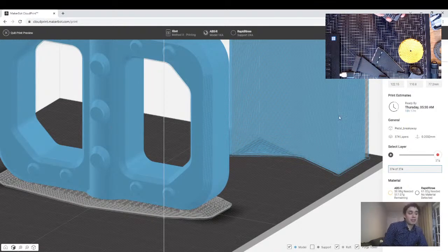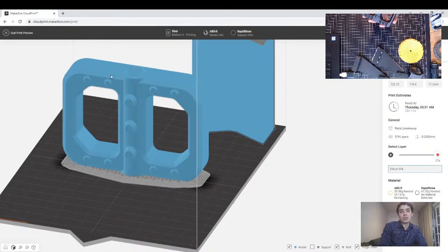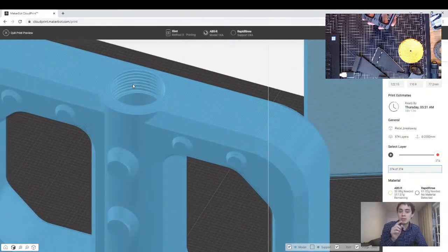However, the layers, as I said before, are now oriented parallel to the way that the force applied to the pedal will be. So that probably is not the best possible option for part strength. It might be better for describing this threaded element, because sometimes the surface finish is not only related to the look of the part, but also to the smoothness of some of the more technical components, like threads, or teeth in a gear. We're no longer talking only about surface finish for appearance's sake, but also surface finish for performance's sake.